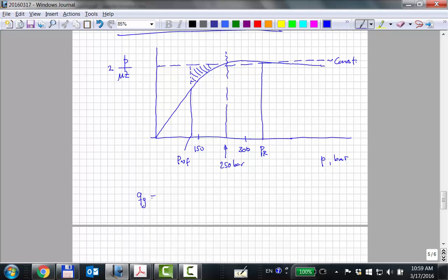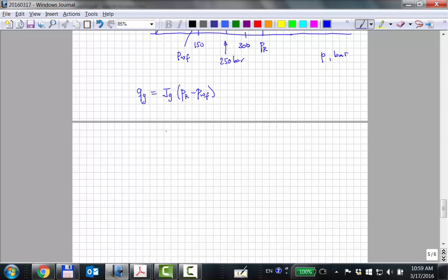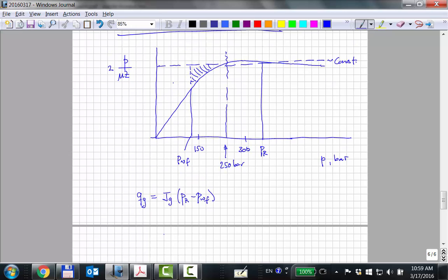So if we think of this as a simple IPR equation where we just use average pressure minus PWF, which is not correct, then if we plot J from this incorrect equation, it would be more or less constant here, when the flowing bottom pressure is up there, but then as you drop down below this, where it starts dropping down here, this thing is going to go down like that, okay?